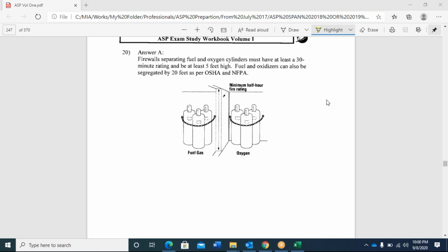In the fire door, it should have FM testing, or a laboratory approved by NFPA, and it should mention the test of this fire door. The fire doors are 2 hours fire rated, and it should be mentioned on the plate, or static plate, stating the fire door resistance and how it is to be inspected.